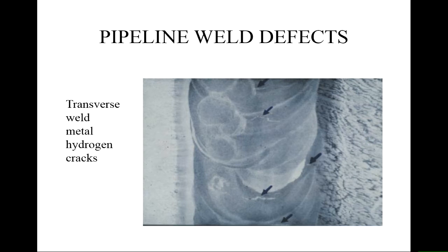And this is actually very difficult to spot in a radiograph because the cracks tend to propagate at 45 degrees, which is parallel to the marks left by different passes. For instance, look here, the crack tends to propagate parallel with those marks, and also this one is parallel with the interpass border here.